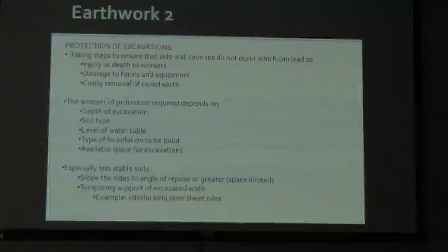When we do excavations, we have to protect them, taking steps to ensure that sidewall cave-ins do not occur, which can lead to injury or death to workers, damage to farms and equipment, and costly removal of caved earth. The amount of protection required depends on the depth of the excavation, the soil type, meaning is it cohesive, is it non-cohesive, what is the friction factor for that particular material, the level of the water table, the type of foundation to be built, and the